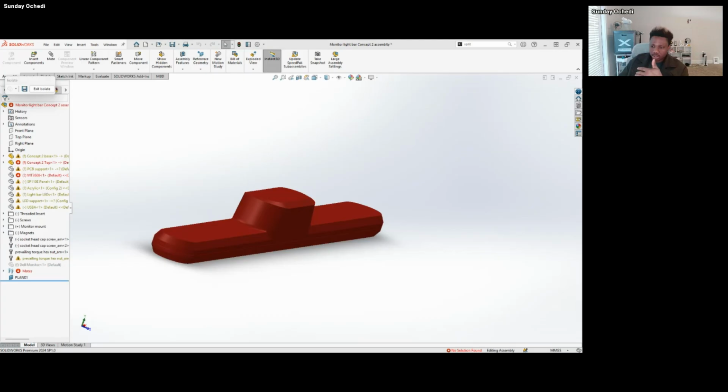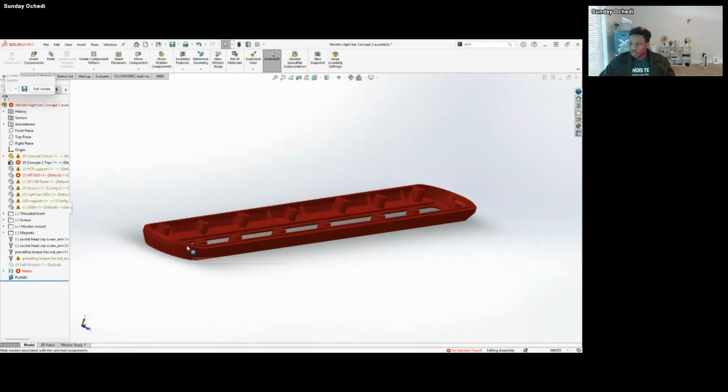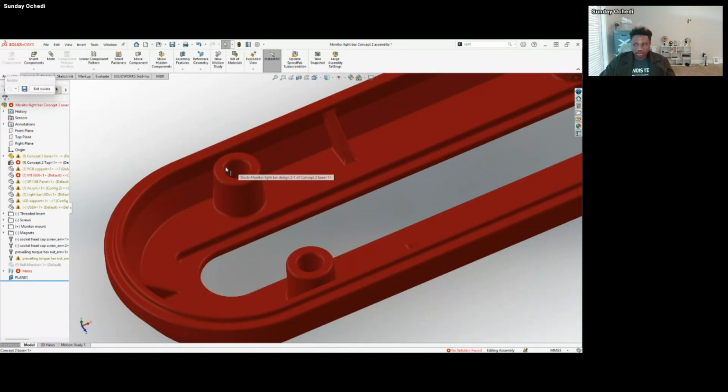But it depends on the 3D printer you're using, the manufacturing method, and within what range you want. The 0.5 comes in when I want clearance, for example for the holes where the inserts are supposed to go in. I take the exact measurement of the insert and then add 0.5 to give slight clearance and ensure it fits in. That's based on my printer.